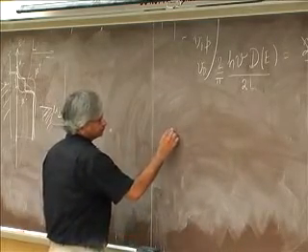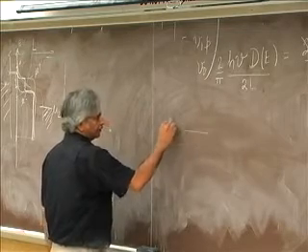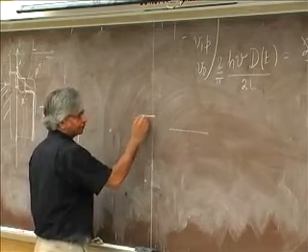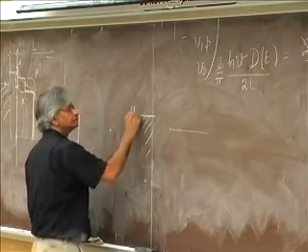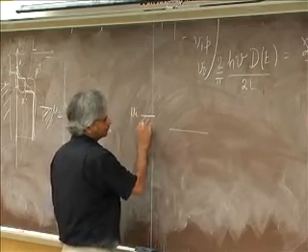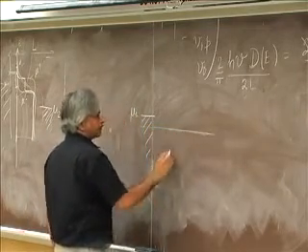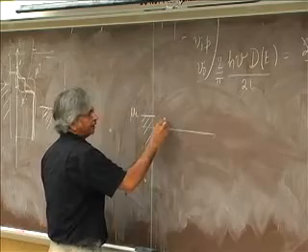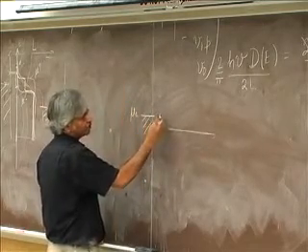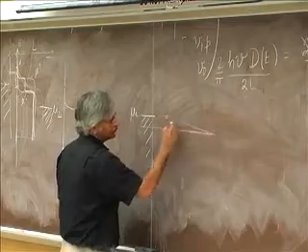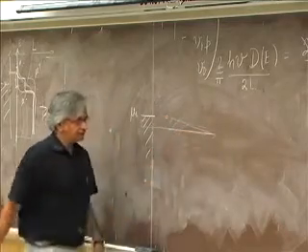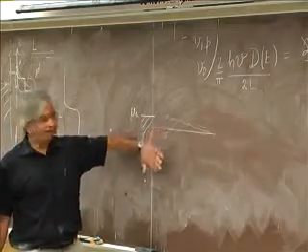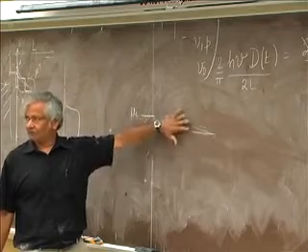Supposing you have a conductor here, and you have put some chemical potential mu1, and the equilibrium chemical potential was, let's say, here, and you have put all these extra electrons in, and you're solving the transport equation, trying to figure out what the electron density is in here. If you do it self-consistently with Poisson, then the bottom of the band will automatically adjust.